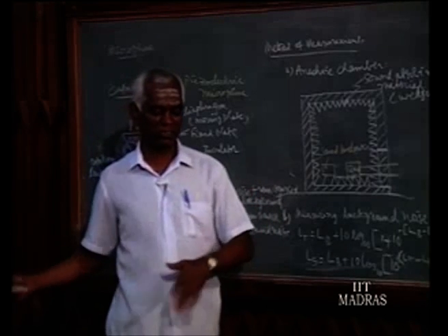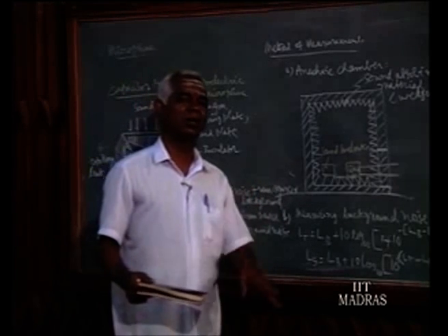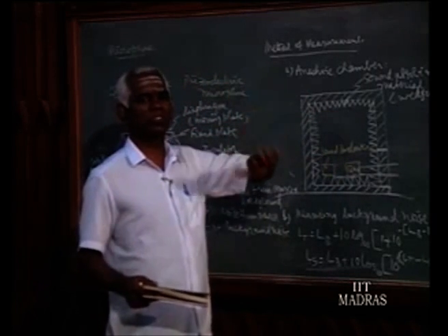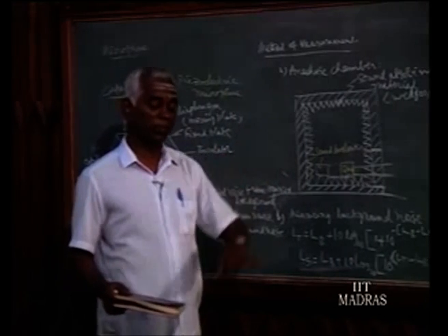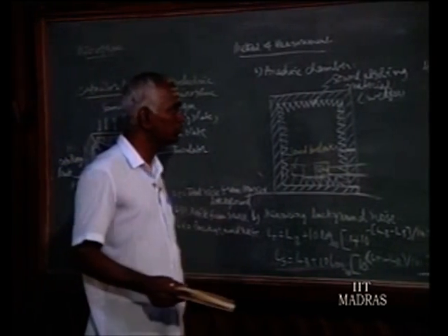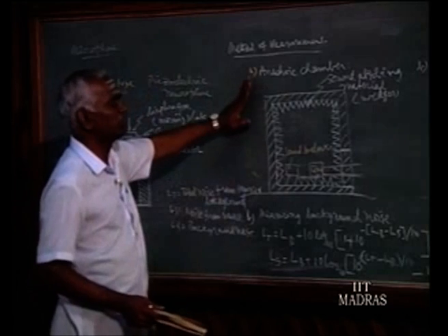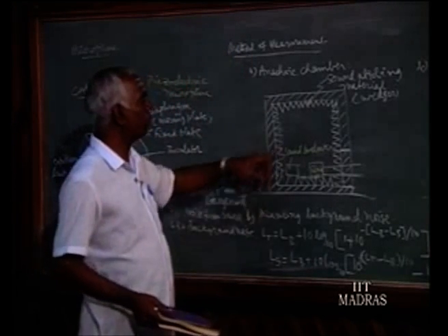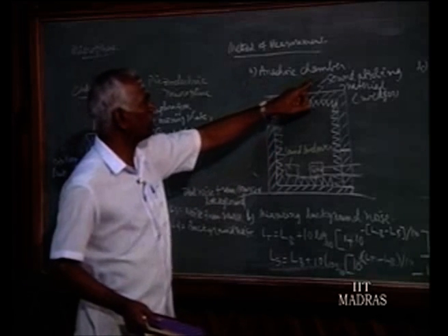If we go double the distance, pressure variation is reduced to half. So in all measurements of sound, we are supposed to quote the distance at which sound is measured. That is one thing. Secondly, I was telling there should not be any nearby wall and all. That will be taken care of if we are using the method using an anechoic chamber.